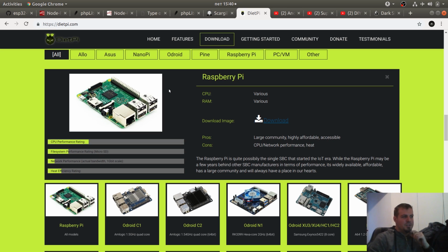But in the newer versions, that file is overridden. Once the initial build is done, it's deleted. So you have to set it up manually, you can't even go through SSH. You have to insert the keyboard and set the wireless SSID and the password manually. So I'm going to find probably a better solution that can be plug and play for you guys. But at the moment, I still haven't found anything. I haven't found the time.